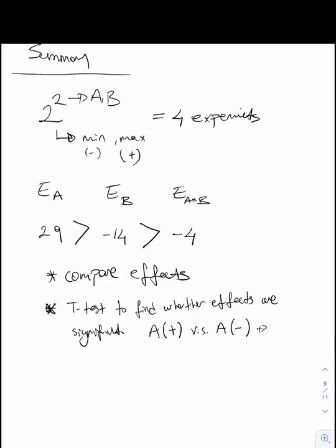And I would say the A, in this case wire resistance, was able to change the system response by 29, and that was a significant effect or not. And I can make these types of conclusions using DOE, different than in normal tests. Just changing A or B, I can now say whether the interaction was also significant or not.